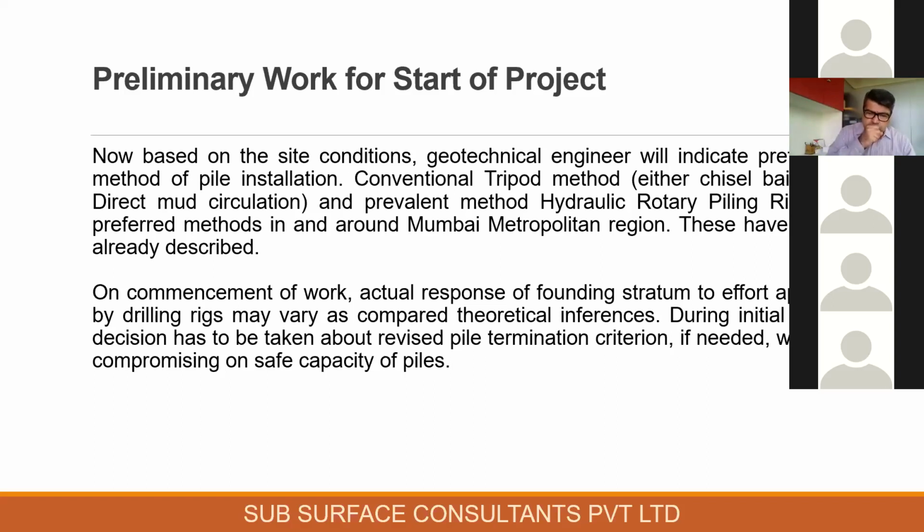But many a time, if the machine is not in good condition, the drilling rig is not in good condition, or the data is not reliable, or somewhat slightly dicey, then you will find that you need to carry out initial pile trials. Only then can you decide upon the pile termination criteria, and we need to revise the pile termination criteria if need be. But remember, all this has to be done without compromising on the safe capacity of piles. Let me go to the next slide.